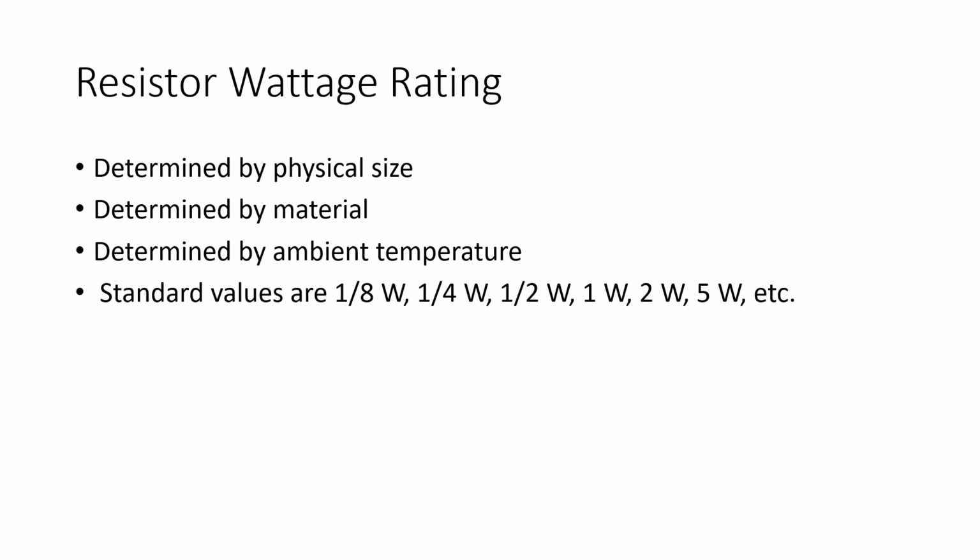So reviewing, the resistor wattage rating is determined primarily by the physical size, but it's also determined by the material. And we have to take into account the ambient temperature for derating considerations. And when we look at purchasing resistors, the standard values for resistor power ratings are 1/8, 1/4, 1/2, 1, 2, 5 watts. And again, when we look at high power applications, we select resistors such as 10 watts, 20 watts, 50 watts, 100 watts.